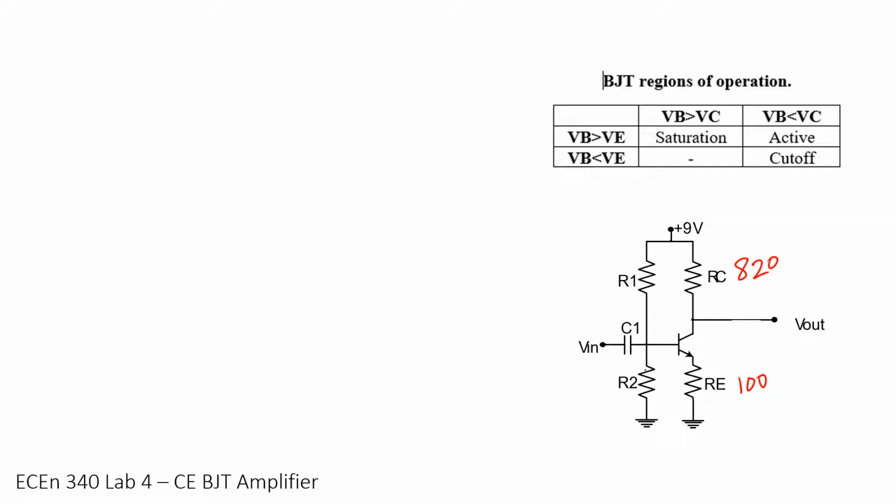Now, what are these resistors here for? It's a little bit convoluted. When we start biasing common collector amplifiers, it's a lot more straightforward. But here we're going to be trying to set a voltage. We're going to think of R1 and R2 as a voltage divider because the impedance looking into this transistor will hopefully be bigger, so it'll be a little more negligible. We can just think of them mostly as a voltage divider, especially if we make RE big enough. But we'll talk about input impedances of transistors in a little bit down the road.